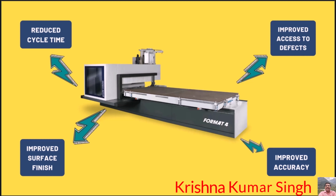Improved access to undercuts and deep pockets. By tilting, the tool can be made normal to the work surface, and the errors may be reduced as the major component of cutting force will be along the tool axis. This higher axis machining has been widely used for machining sculptured surfaces in the aerospace and automobile industry.